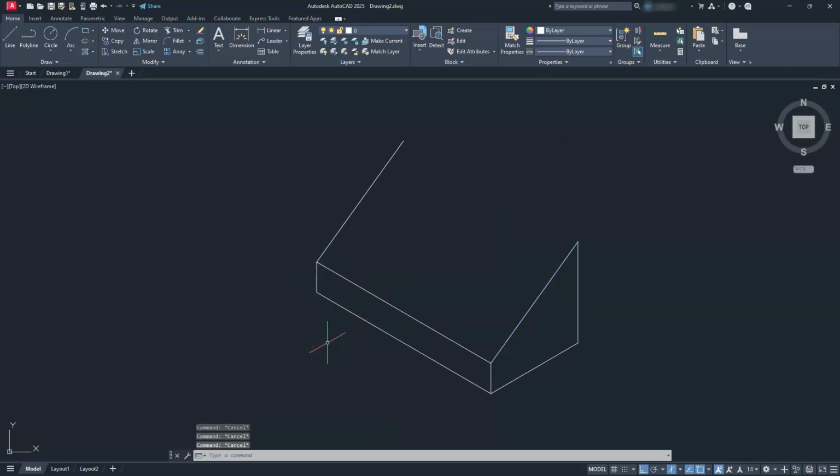Okay, let's go ahead and switch back to isometric left. Next, let's draw a line going from this direction over 20. Let's escape out of there and do the exact same thing here on the other side. So draw a line going this direction, 20. Okay, so here along the bottom, we know that it intersects with this plane over at 35.